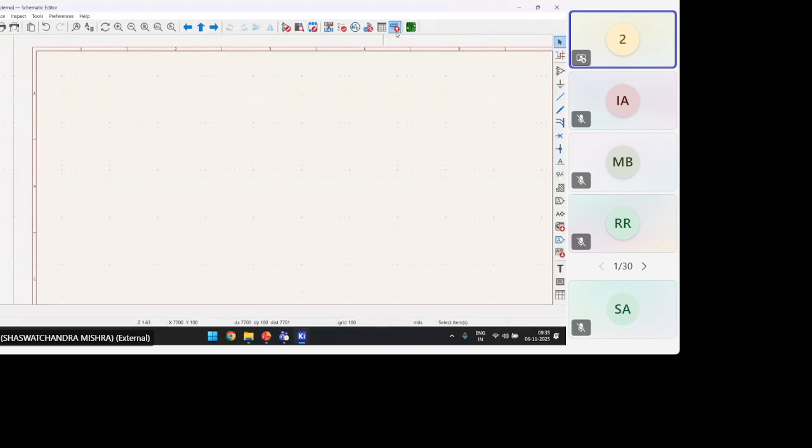Okay. Next is the PCB editor. From here, you can go to the PCB editor page. Okay. So this comprises all of this. Then from here you can print our circuit, and here you can see there are 3 options. There is inches, there are mils, and there is millimeters. I suggest you stick to mils, and the grid should be 100. Okay. You can change them, but I suggest you stick to 100 for this specific circuit.